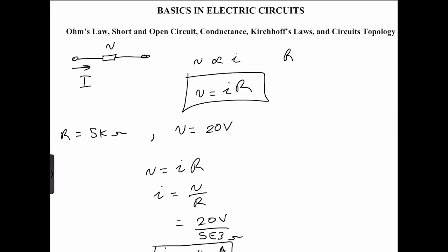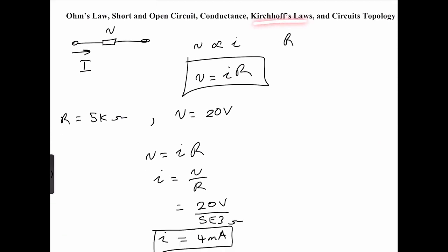Next, I think we have the KCL and KVL, Kirchhoff's voltage and current law. So for these, we can then go ahead and just write down the current law first, KCL. So the algebraic sum of currents, let's just write that down first. So the algebraic sum of the currents entering a node or a closed boundary is equal to 0.